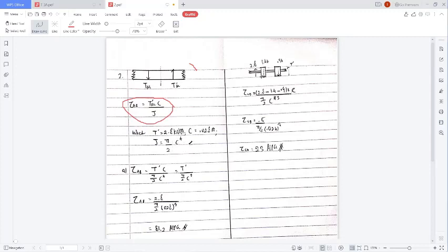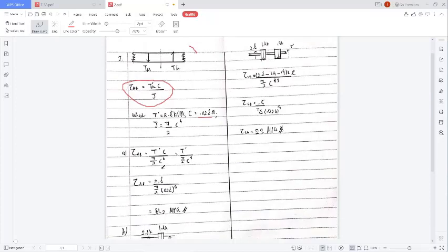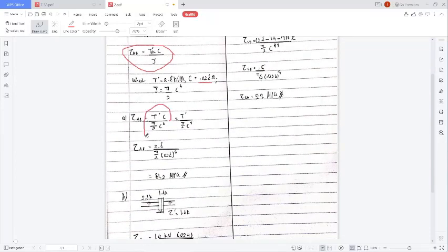The value of C, as you may guess, is just the same as 0.028 meter. So the value of C for the polar moment of inertia is the same as the value of C in the upper side of this formula. So you can simplify this equation even more by cancelling out the value of C in the upper side against the below. So we will get tau prime equals P over pi over 2 C to the power of 3.